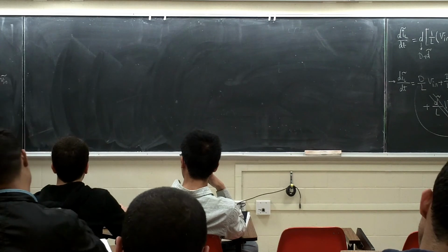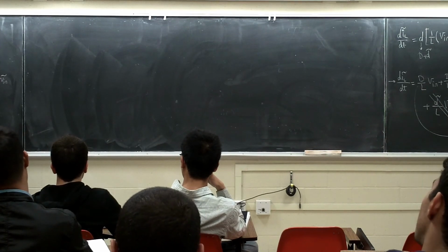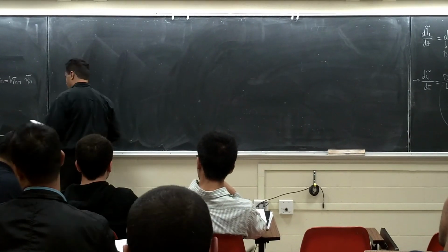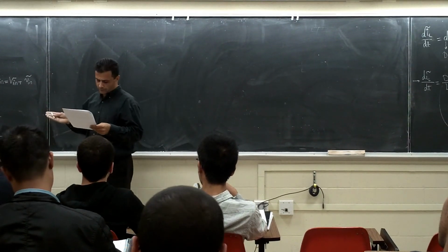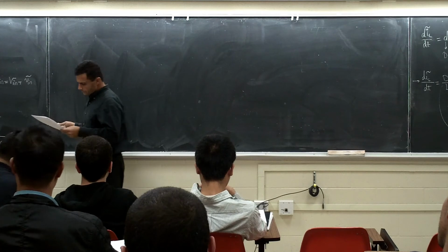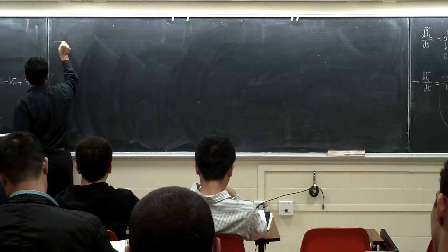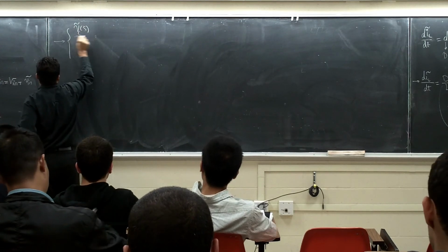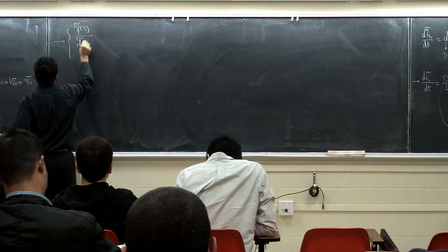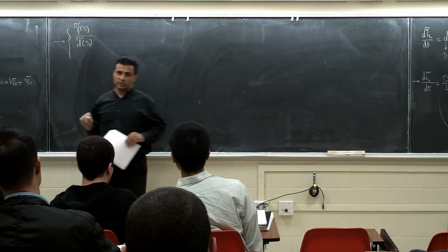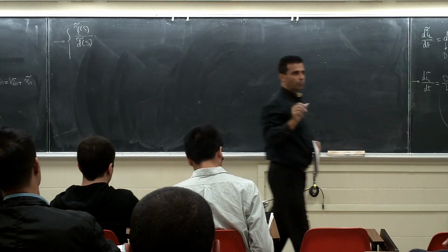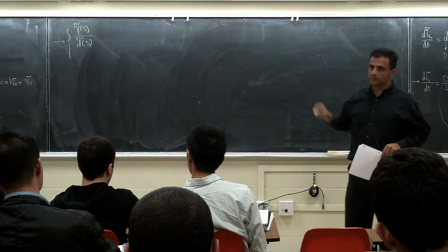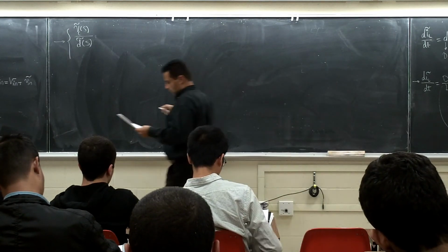Now we have this equation. We can go find our transfer function. For example, here I'm going to find all combinations. For example, VC tilde(s). This is the one most of the time we are interested in, if we are going to control the output voltage. Because VC is VO, right? VC is VO. So this one is going to be